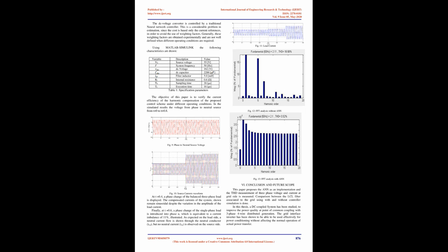In power systems, ANN controllers are very well known for their ability to diminish harmonics. In the proposed model system, the Adaline, adaptive linear element, structure of the ANN controller is utilized in the shunt active filter, which compensates for current control as a result of its simple and straightforward structure and quick response.